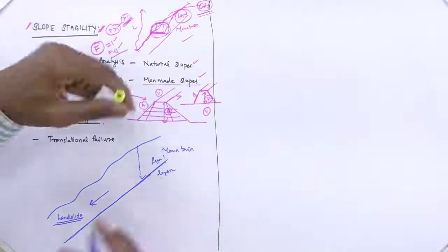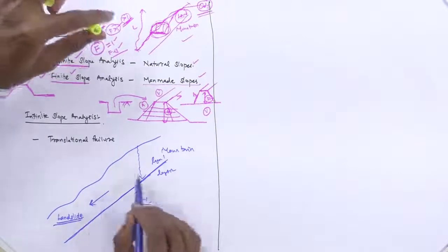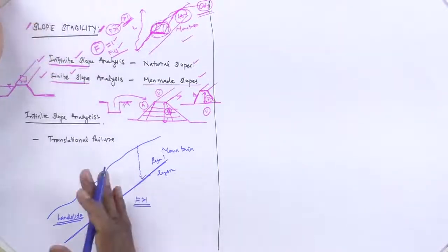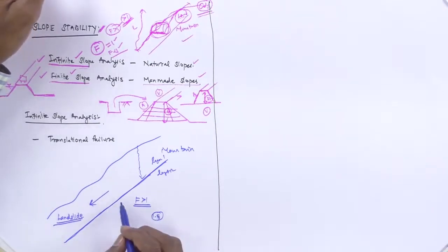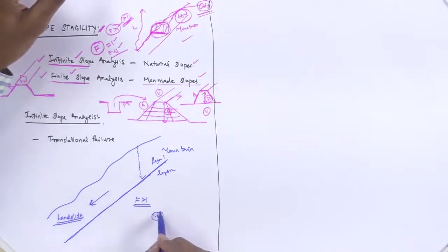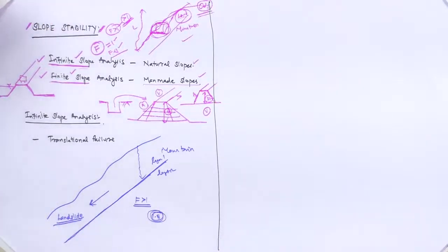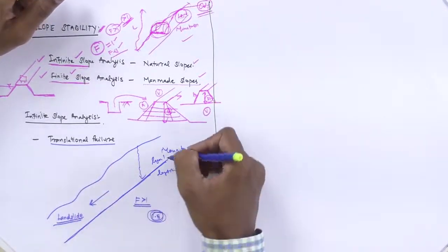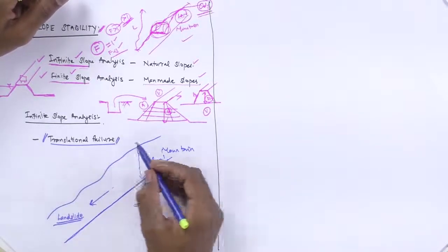When the factor of safety is greater than 1, the slope doesn't fail. How much safer is it? Say 1.5 times, so it has the ability to stand 1.5 times against the landslide. So that is what a translational failure is, moving in a linear direction.